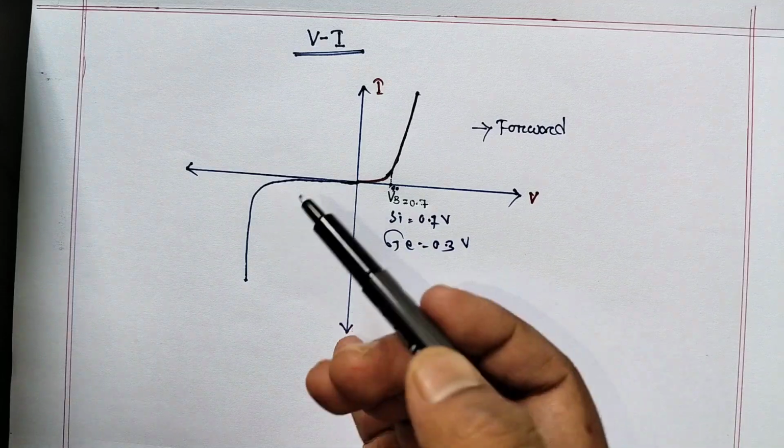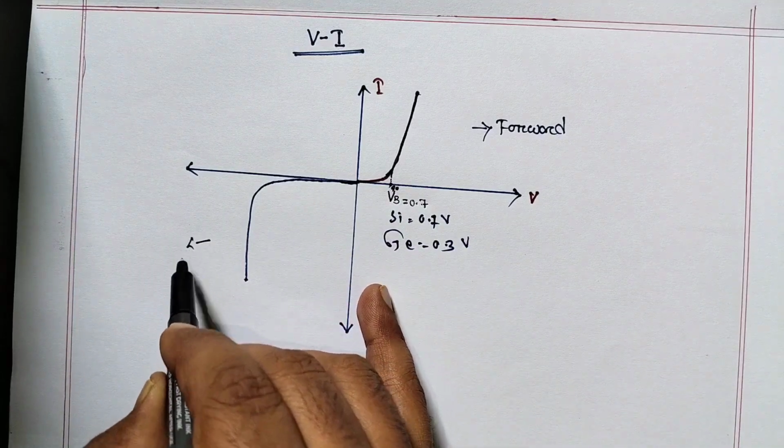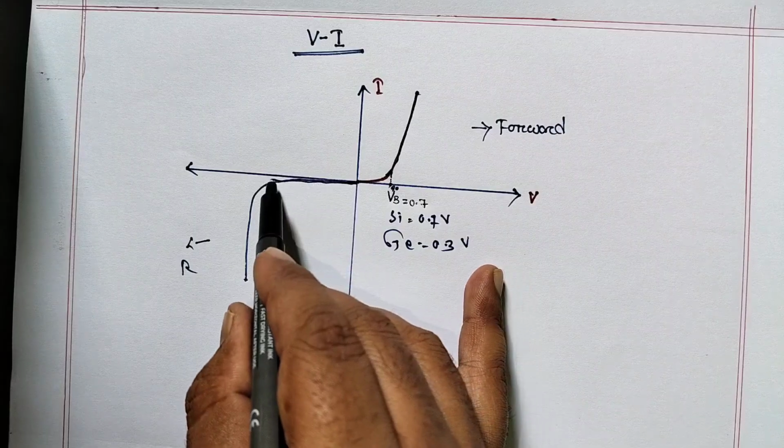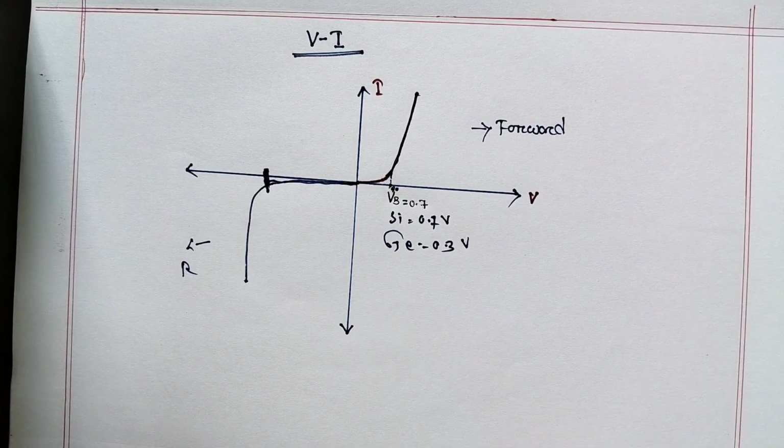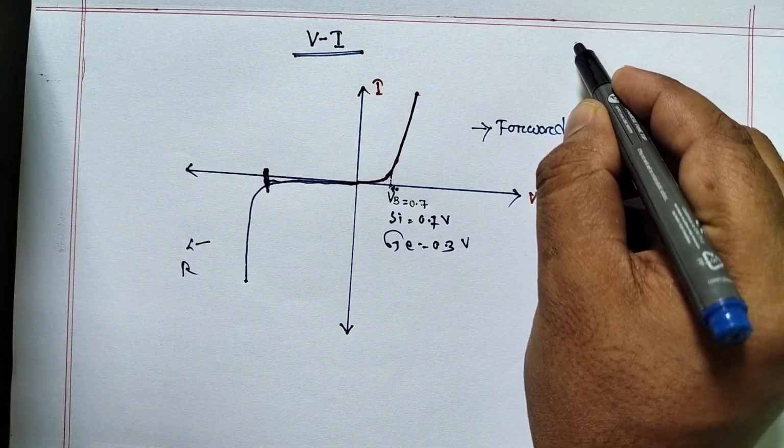This is the reverse bias condition. What happens? In reverse, at a certain high voltage, this is called the reverse breakdown voltage. After that it can conduct, but it will be damaged. While buying a diode or using it practically, we can check the data sheet to see the breakdown voltage, the reverse breakdown voltage, and the current rating. According to this we can use it for our circuit.